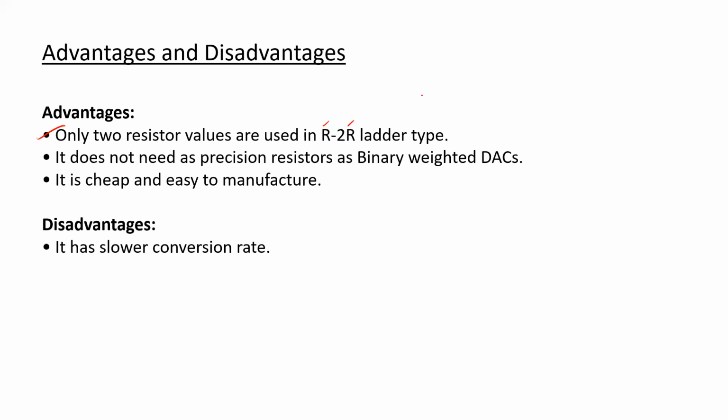So using the same manufacturing technique, multiple quantities of this resistance and multiple quantities of this resistance can be obtained. Whereas in case of the previous digital to analog converter circuit, it was a high requirement that the resistors had to be very precise and accurate. Now for this case, it is not.